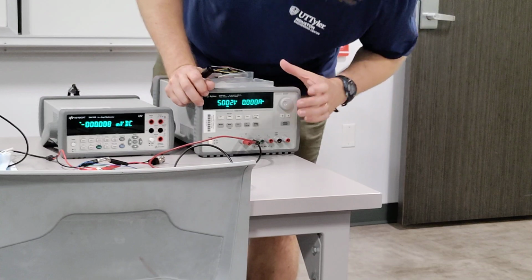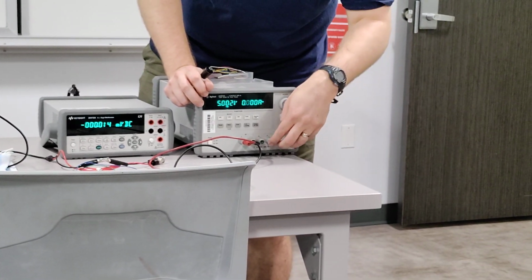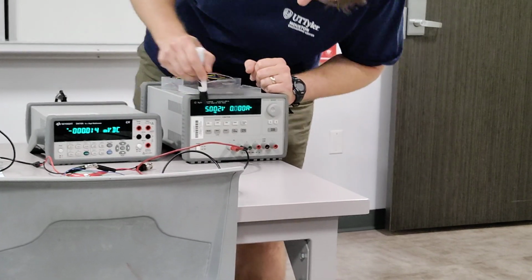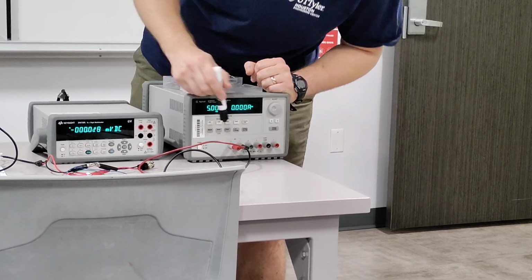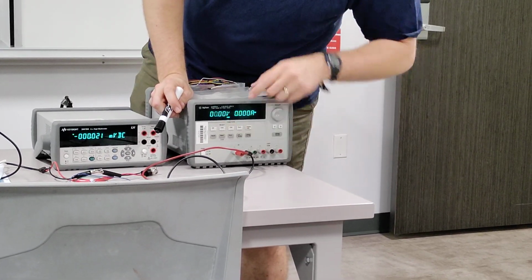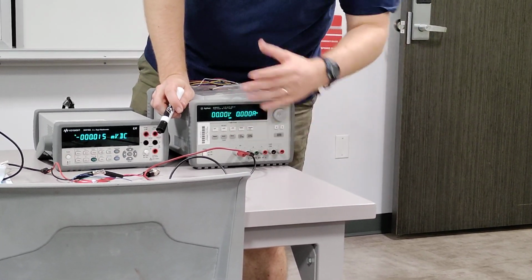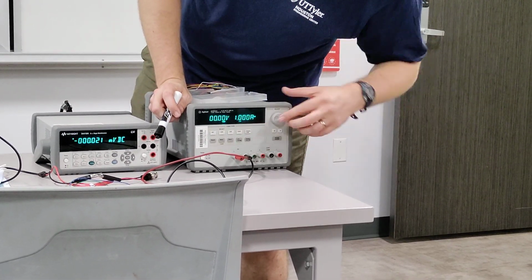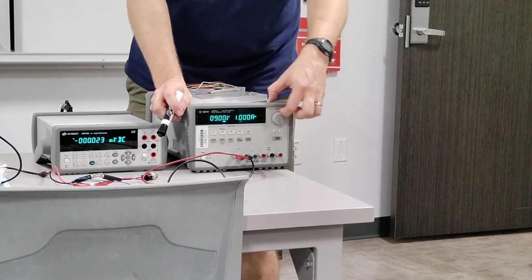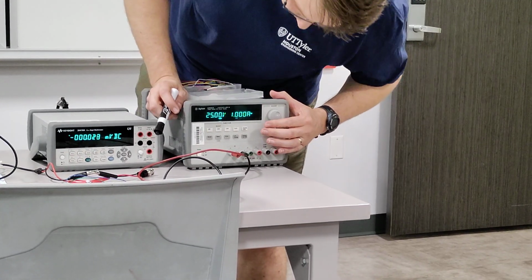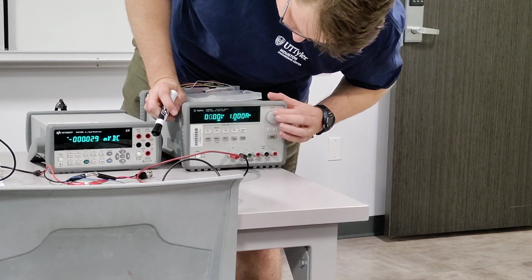Okay. The way you adjust the other channels is with these 3 buttons here. There's a plus 6 volt channel here, and it shows you that you're adjusting plus 6 volts. And then there's a plus 25, and the display updates, and minus 25, the display updates. And you do the exact same thing. So like plus 25, display limit, and I've got my voltage, and now this will go all the way up to 25 as opposed to 6. Which we're not going to do today, because we don't want to break anything.